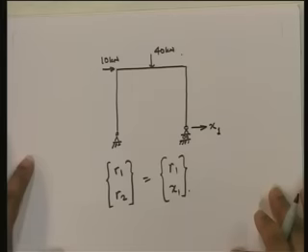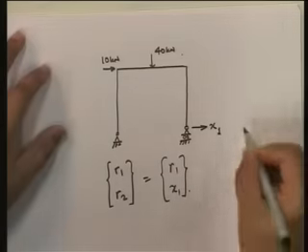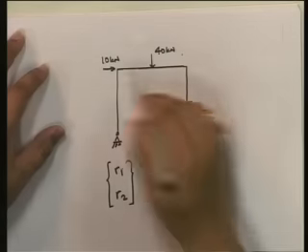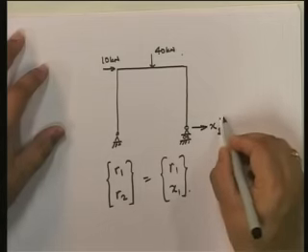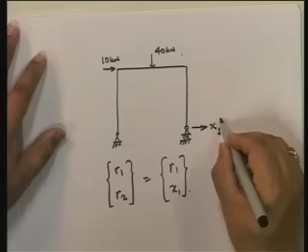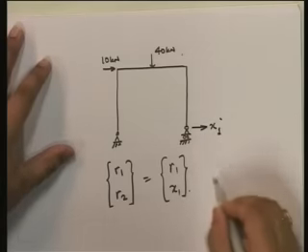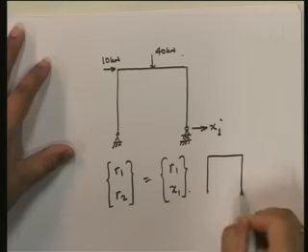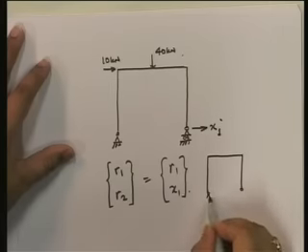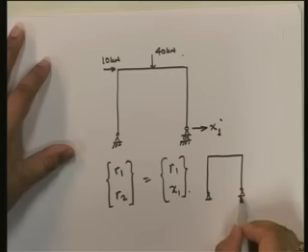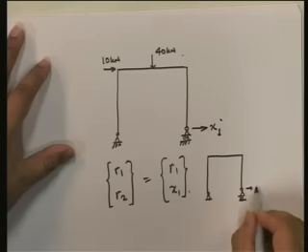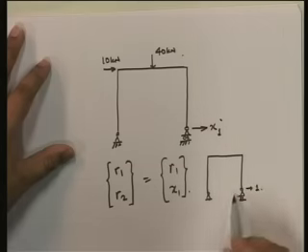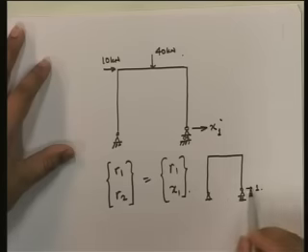Okay. Now, so you would find out X1 here, right? You would find out the displacement here. That's the step. I'm just going through the steps. What is the next step? The next step would be you apply a unit force over here and find out the displacement at this point, right?